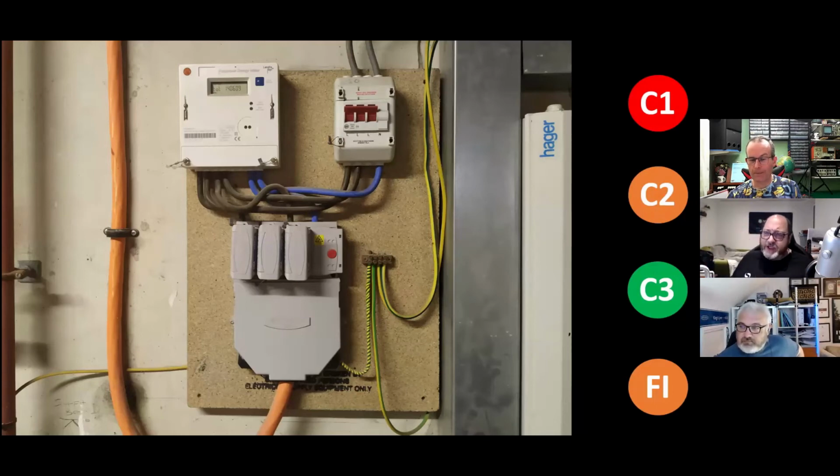Again, when you're talking about the use of a system, if you've got people in the home and the lights aren't reliable, then I can see how you can easily C3 that or FI that. C2, if the absence of lighting creates a problem, or is it just lighting that's affected? It's basically lighting. If the lights are on in the flat, they know when the lift is used because it dips for a minute and then goes back.